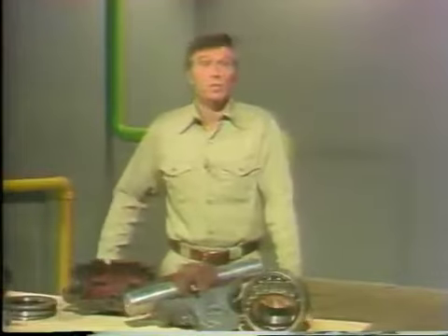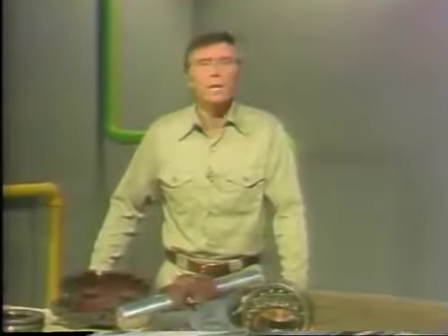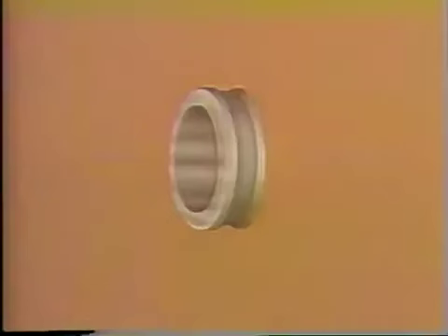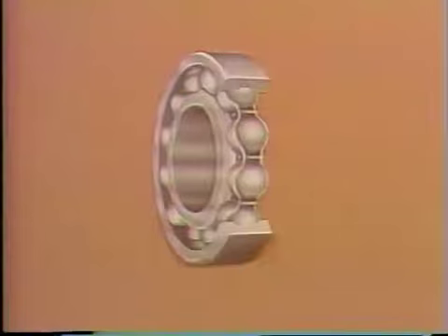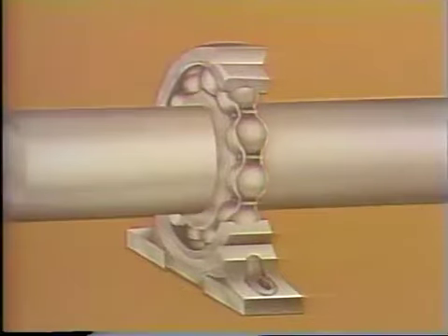Well, so far we've been looking at sliding surface bearings, but rolling contact bearings can also be used to prevent radial and axial movement. Let's look at the parts of a common rolling contact bearing. First, there's an inner ring. Then there's rolling elements that are held in place by a retainer, an outer ring, and a housing. The outer ring is attached to the housing. As in most bearings, the housing is attached to a stationary structure. In this bearing, the inner ring is attached to a shaft. The inner ring and the shaft rotate together while the outer ring remains stationary.